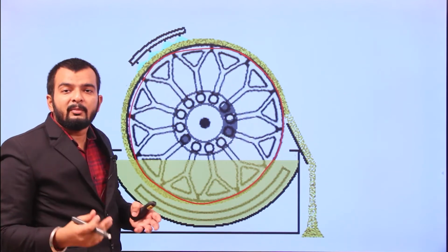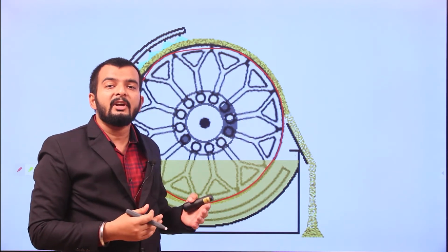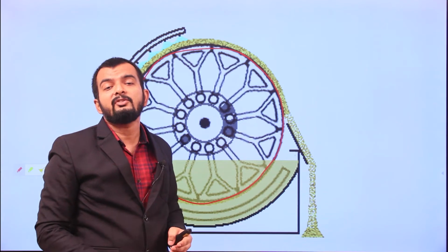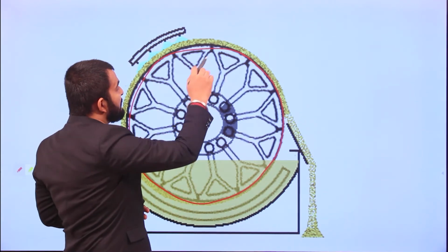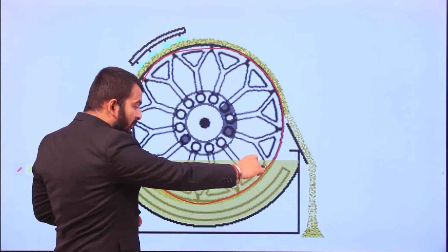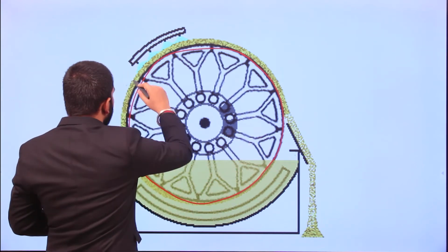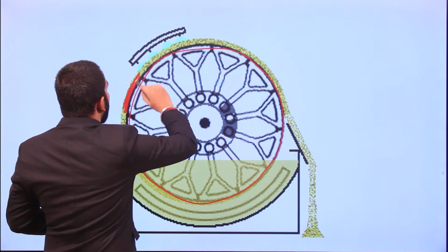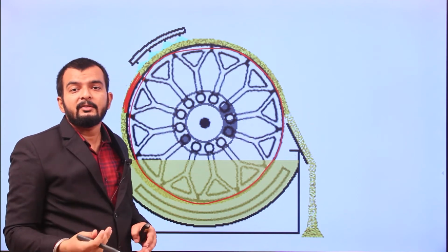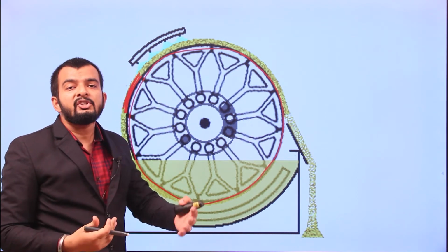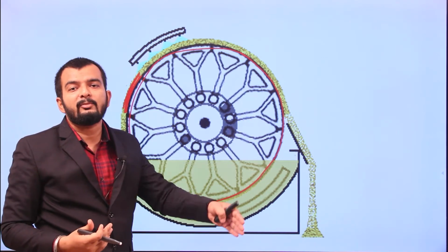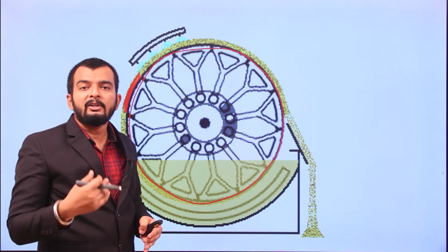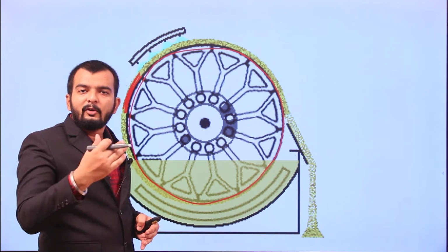With the help of the steam, the temperature of the surface can be raised to about 200 degrees Celsius. So when the temperature is so high, this thin layer which is formed at the surface will get dried very easily. Since it is a very thin layer, the moisture migration from the surface of the thin layer to the atmosphere will be very quick. All the moisture or the water will evaporate quickly.